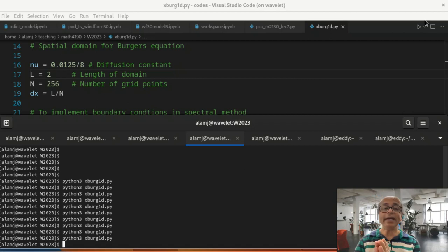So when I increase nu, actually this is in view of fluid mechanics, if the Burger's equation represents the Navier-Stokes equation, then increasing L, the domain size, is equivalent to increasing the characteristic scale or increasing the Reynolds number. Also, decreasing the viscosity is equivalent to increasing the Reynolds number.